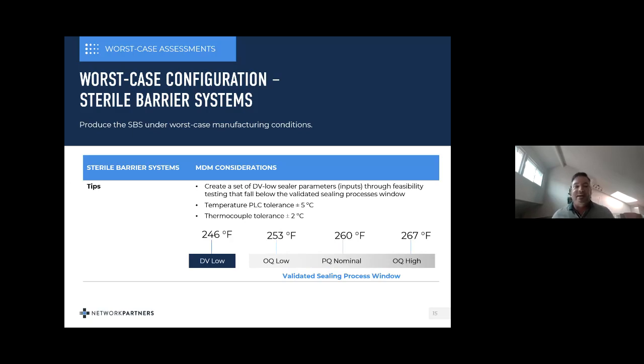After that, come out to ambient laboratory temperature for 4 hours, put it back into the other extreme, 40 degrees C at 90% RH for another 8 hours. And then before I go through and do all the distribution hazard simulation testing, I let them get acclimated to 4 hours and then go through all the testing. This kind of avoids that thermal shock that we're talking about, because I've seen it before with PET-G trays where you get these temperature extremes, you go into one temperature extreme, take it out, immediately put into another. So you're kind of asking for failures.